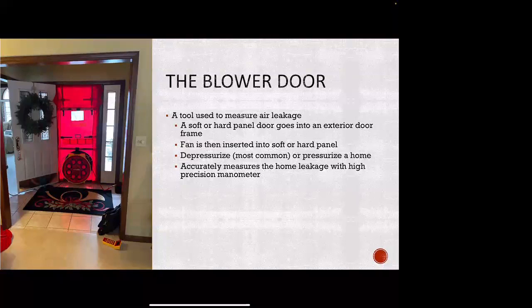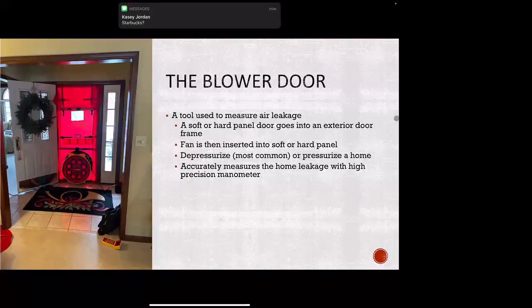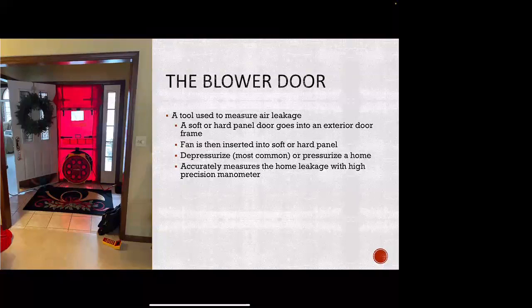And why we would pressurize that home is if someone had allergies or was very allergic to potential mold spores or anything that we could be bringing in through those air leaks. So that is very, very important to know which way we're actually going to perform that test. And that's up to the technician or the specialist that's out there actually testing the home.